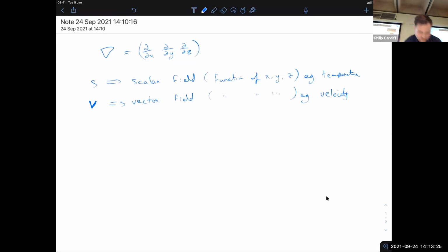And then you can also have tensors. A tensor, you can think of it as a 3x3 matrix, except it has symmetric special properties. So a tensor, you can also think of as just 3 vectors. So you can define the stress at every point in the material in your space. So that might maybe not be as natural for a fluid.